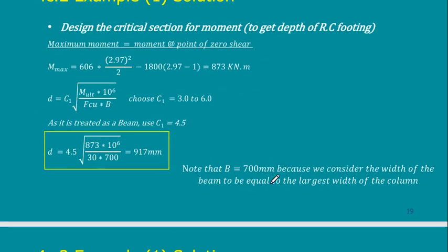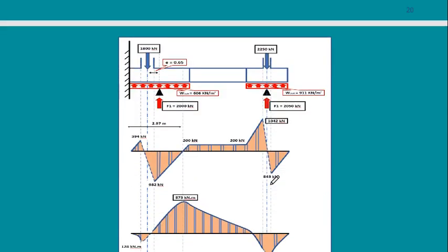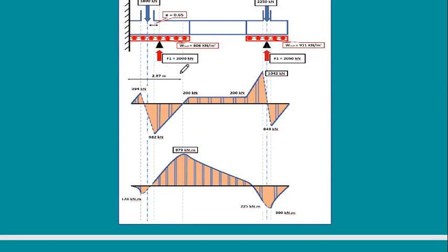I'm just going to go to this drawing. If you look at this drawing, these are the blue arrows, this is the strap beam, and these red arrows are equivalent to the blue arrows. I transferred the red arrows from being concentrated load into distributed load coming from the soil. These small red arrows are distributed load, and this is the same for the other one. So now I need to design a beam.